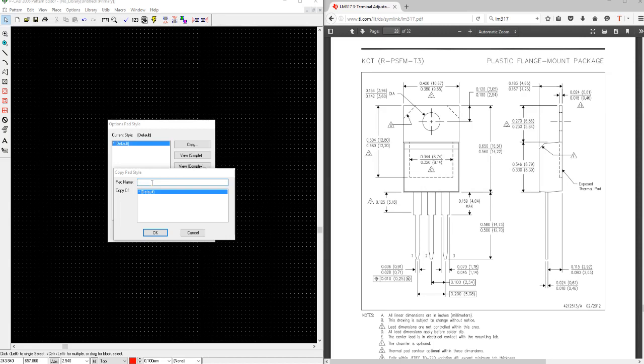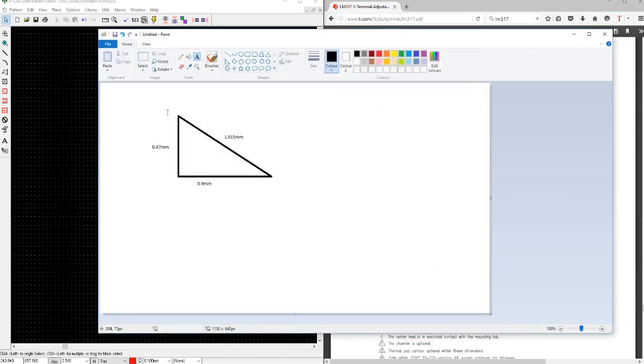So we're going to start off by saying it's TH. TH for through hole. Surface mount will be SM, followed by colon, then followed by what the pad is. So in this case we are going to basically make a round rectangular pad. So we're going to go RR, round rectangular, followed by the dimensions X for the X axis and the Y axis. Now if we look at this pad with this calculation again, we saw that we need a pad of at least 1.2, so I said 1.3.